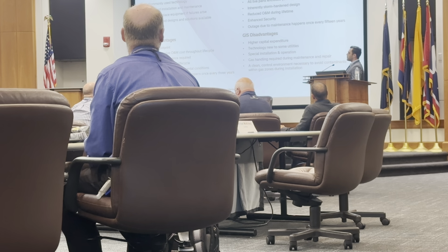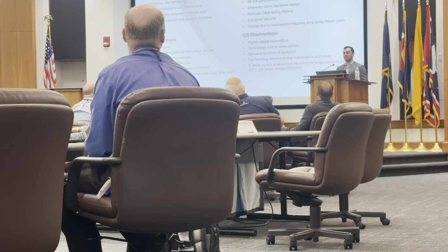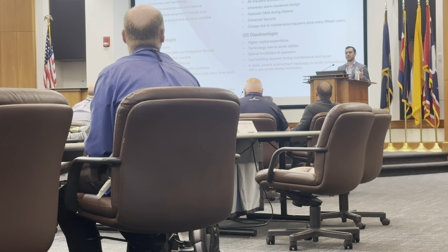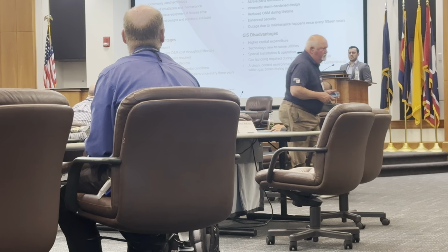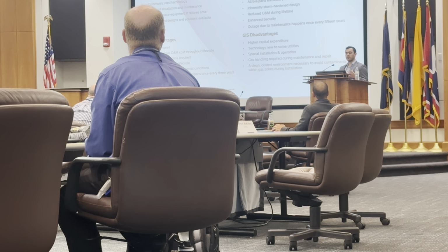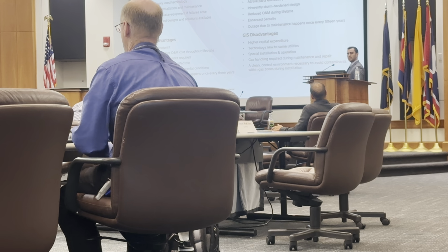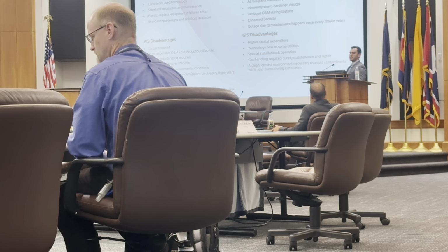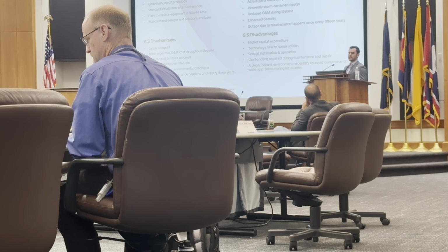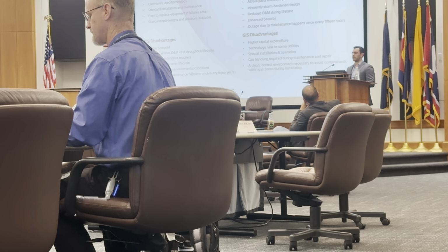All right. Now for GIS advantages, the overall cost of ownership is one of the advantages. However, when you're looking at the capex initial investment for GIS, it's going to be at its highest. When you're comparing both solutions, the GIS is a full solution rather than when you're looking at the AIS. Typically, you're looking at the dead zone breaker, which is relatively cheaper than a GIS. Right? A GIS, you're reserving and lowering your preparation costs. You have less operation maintenance during the whole life cycle, and it has enhanced security, not only for the GIS but also for the substation, which is a growing topic nowadays as well.